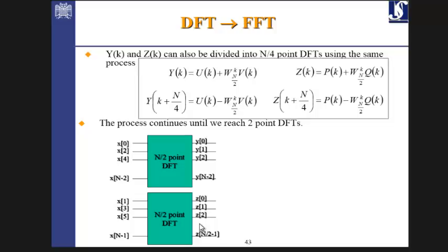They developed different types of FFTs, and now we have a dozen algorithms to implement the FFTs, and some of them are already in MATLAB. In MATLAB, if you want to take the DFT, just write down FFT. For 1-dimensional data, FFT works. For 2-dimensional data, FFT2. For example, you have an image, and you want to take the 2-dimensional FFT of the image, you write down FFT2, that's all, and it's implemented.